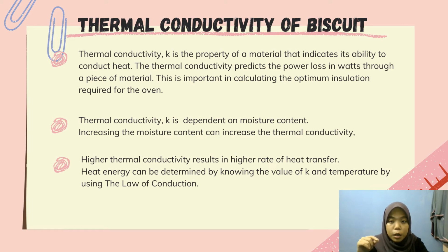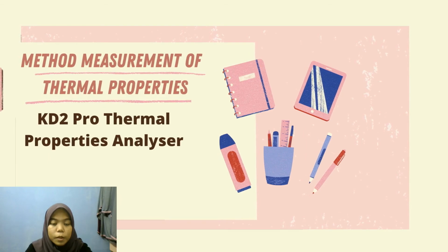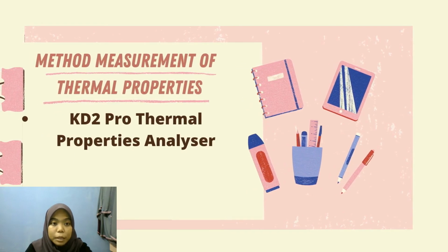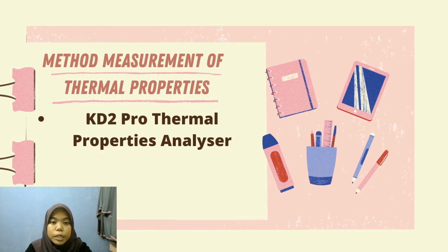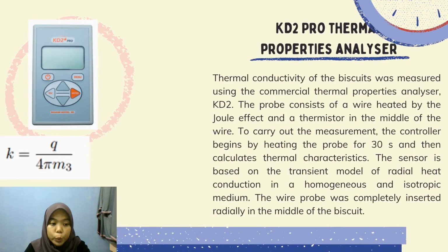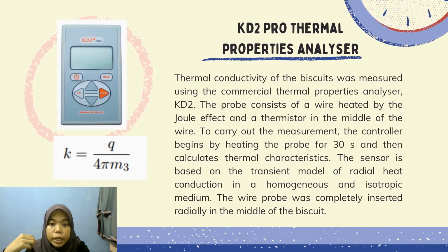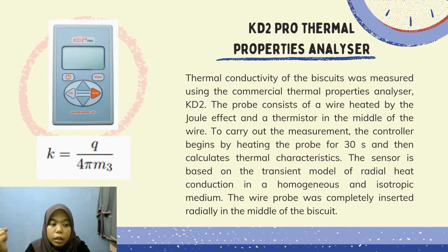Next, I will present about the methods of measurement for thermal properties. Thermal conductivity of the biscuit was measured using the commercial thermal properties analyzer, which is KD2 Pro. KD2 Pro is a battery-operated, manually driven device that measures thermal conductivity and resistivity, volumetric specific heat capacity, and the thermal diffusivity.